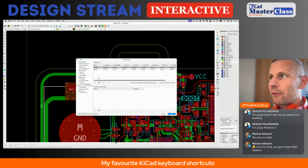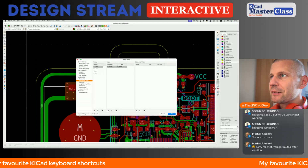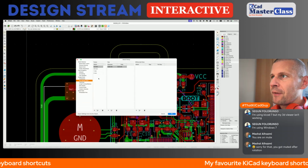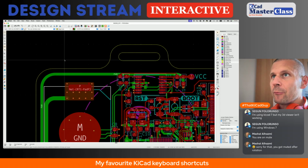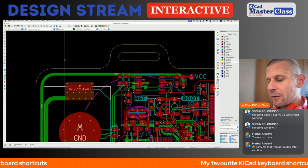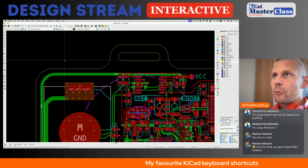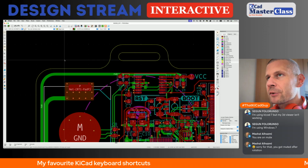Go to File, Board Setup. Here are the predefined sizes, and you can see I have entered 4 sizes, and when I'm pressing W, I'm going through this array. When I'm holding Shift and hitting W, I'm going in the opposite direction through that array.